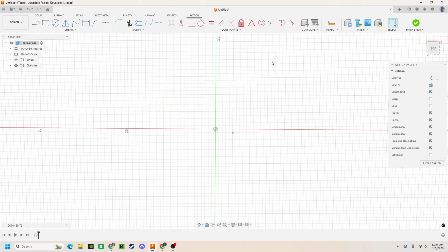The next constraint we will look at is the fixed constraint, which is this lock in the Constraint tab. We rarely use this constraint simply because it is not parametric, and it has no mathematical significance. It essentially just locks the position, angle, and length of a line without other constraints. This means that it is very difficult to change.